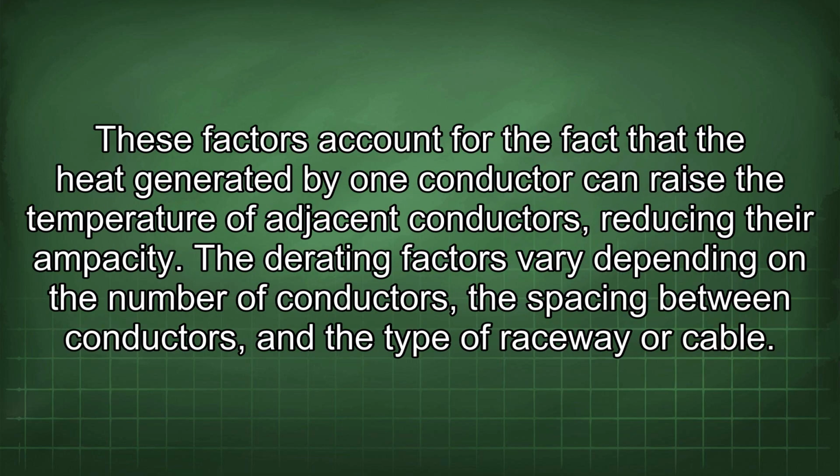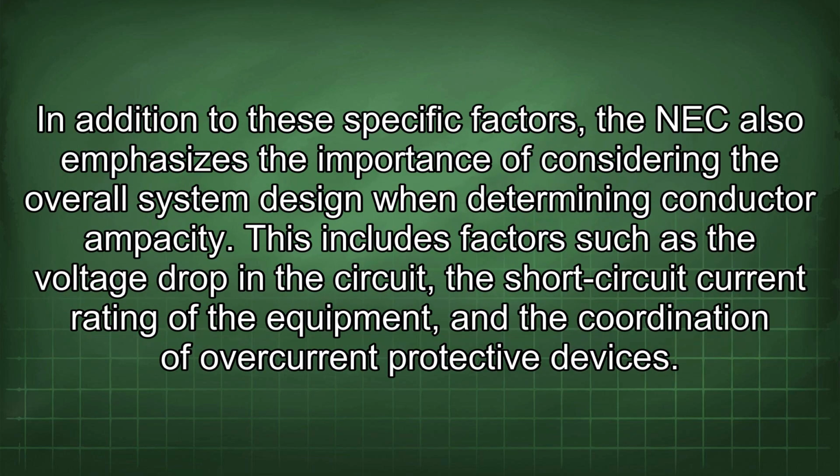These factors account for the fact that the heat generated by one conductor can raise the temperature of adjacent conductors, reducing their ampacity. The derating factors vary depending on the number of conductors, the spacing between conductors, and the type of raceway or cable. In addition to these specific factors, the NEC also emphasizes the importance of considering the overall system design when determining conductor ampacity.